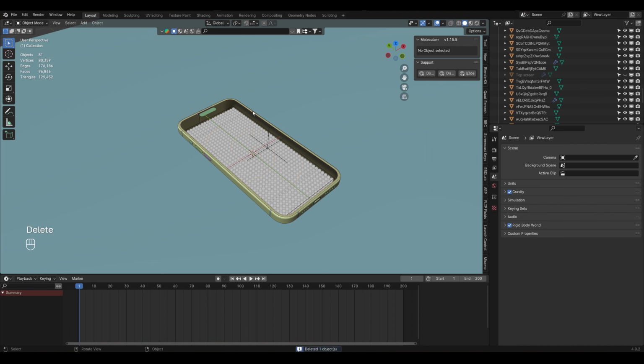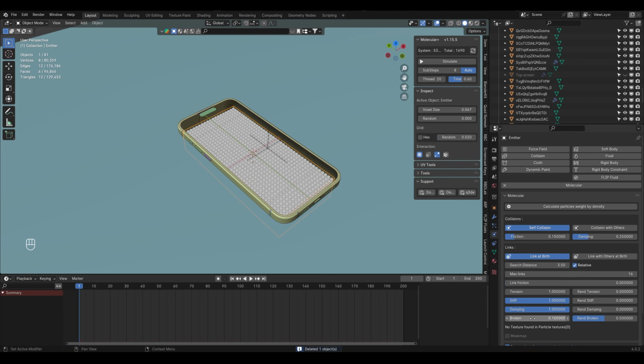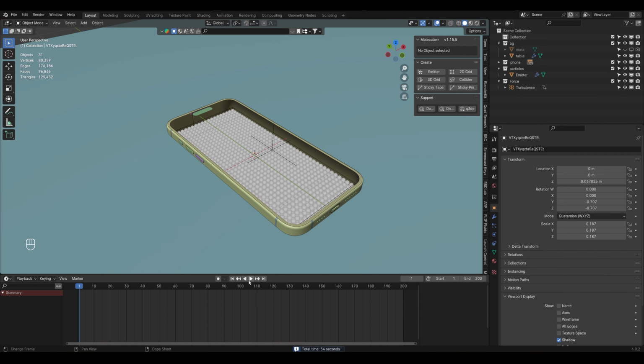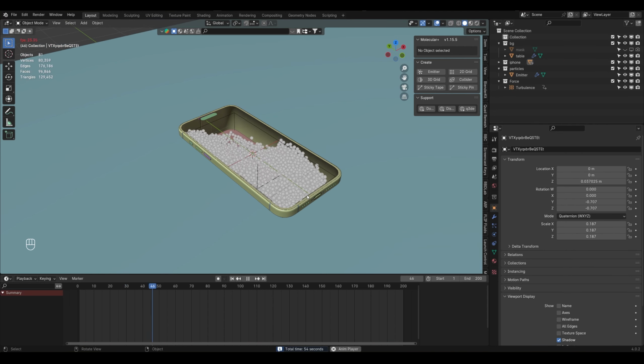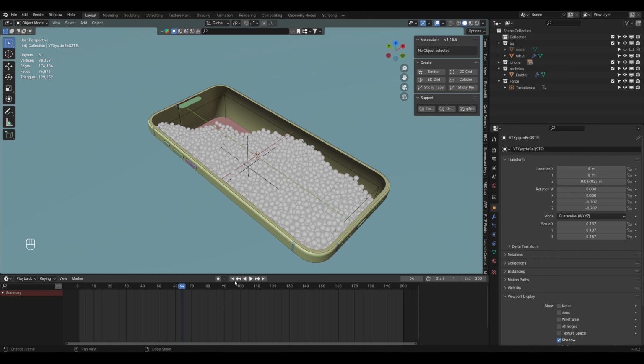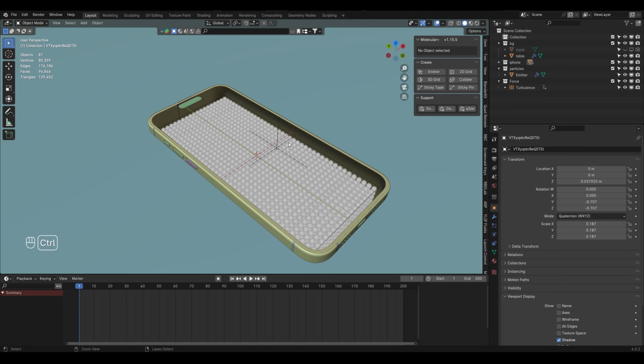Maybe I will just delete this. I will select this again, and in this broken, maybe I will go with 0.05, and I can also randomize the stiffness and damping. And broken, I will also make it 0.7. Simulate once again. This is still moving a bit fast, but yeah, I will go with this one for now. Based on your preferences, you can change it later also.